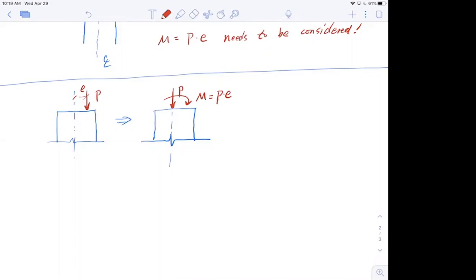Okay, so let's take a look. When I have a bending moment going this way, and I have a force right here in the center, I actually have a stress distribution. I'm going to draw the stress distribution caused by this action in red. Now this side would see tension, and the other side supposedly will see compression, and then we connect them through here.